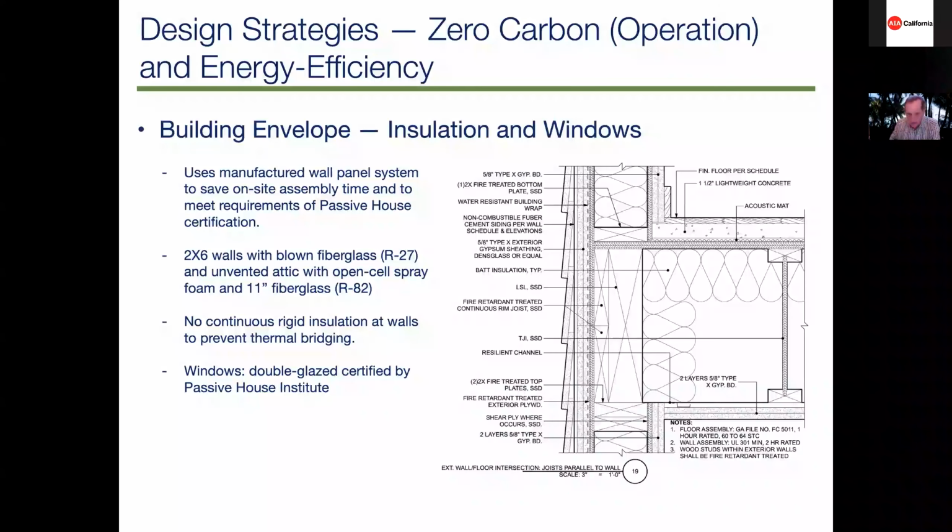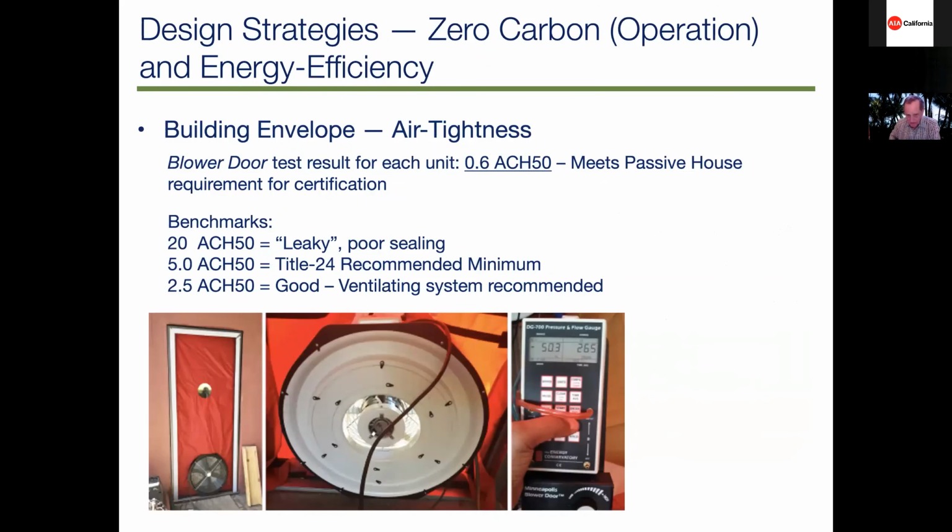As it turns out, the manufactured panels had a problem with quality control, let's put it that way. The assembly of the panels, the connection to the floor, and also the fact that the floor was somewhat uneven when they poured the concrete, meant that it didn't seal well underneath the plates.